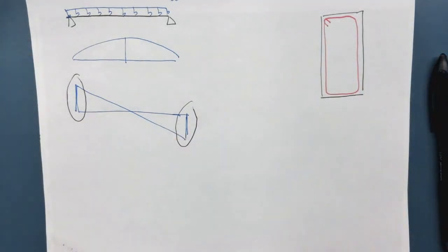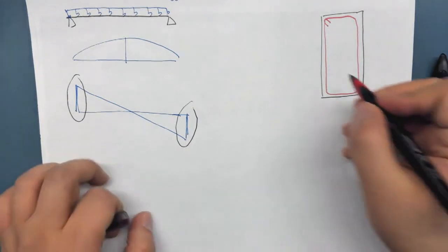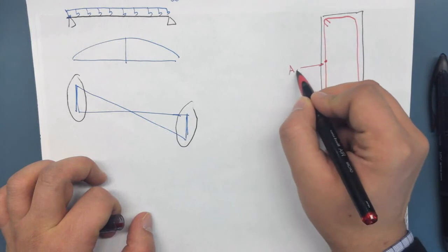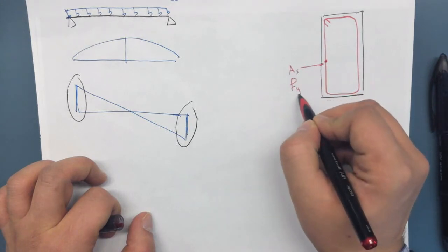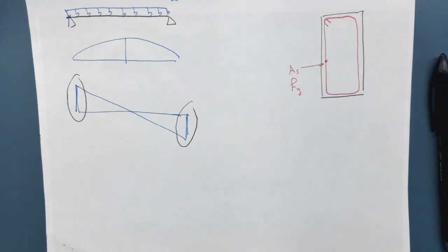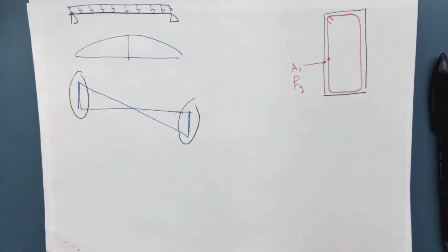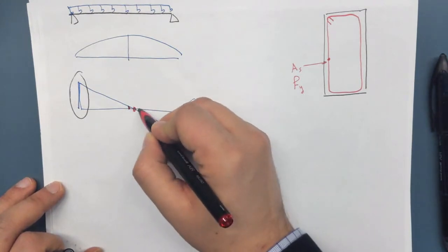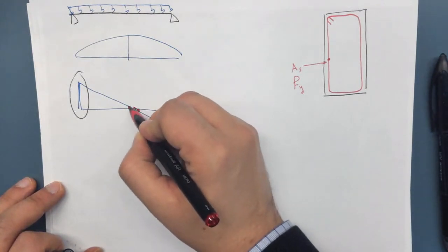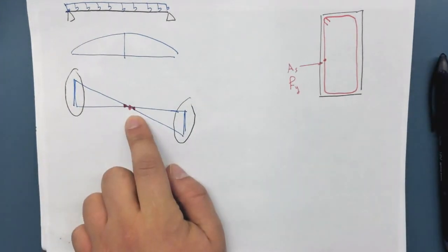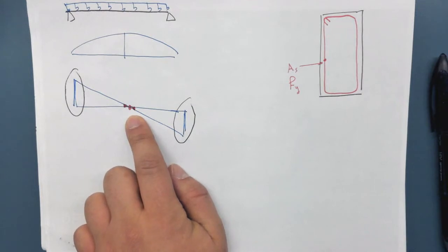So those stirrups have a specific cross-sectional area, let's name it AS, and have yield properties, FY. What is happening is, if you look at this diagram again, you will see that there are some regions in the concrete sections that have almost no shear. It doesn't make any sense to have stirrups in a section that doesn't have any shear. Okay? You don't need it. There's no shear, there's no need for reinforcement.